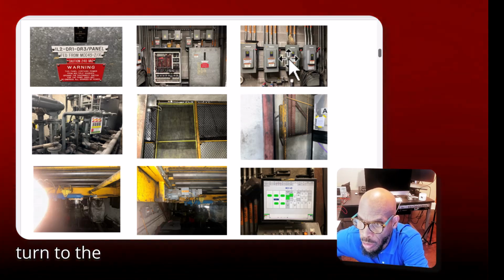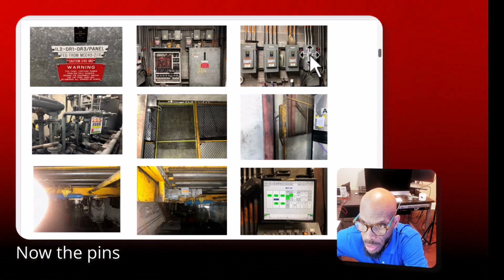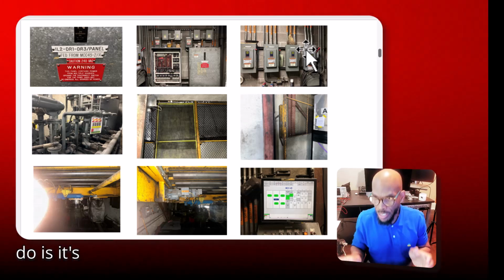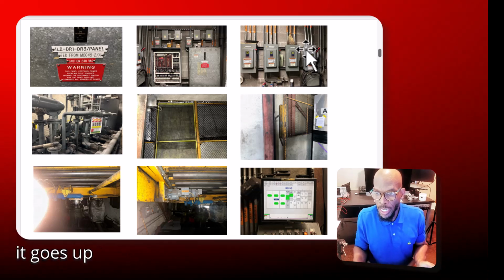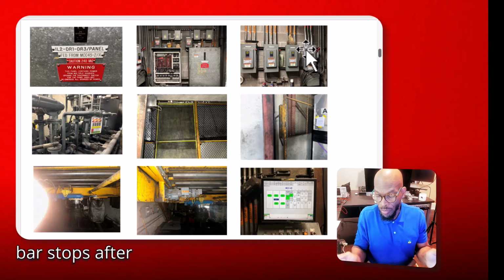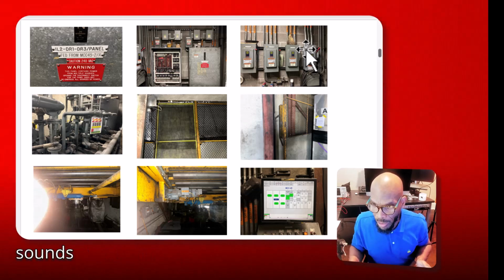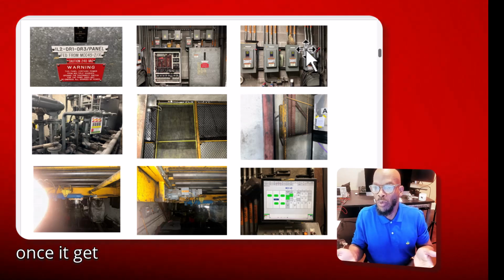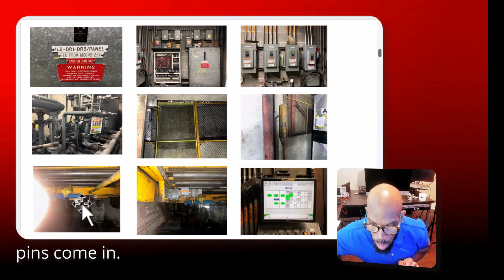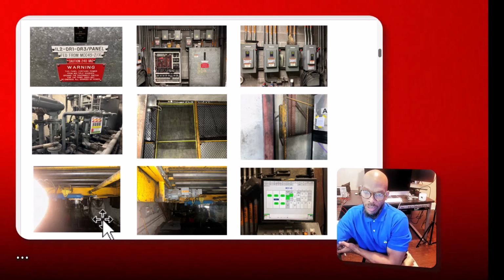Then if you turn to the left on the adjacent wall, you will see the disconnects for the pins. Now the pins go out and come in depending on what floor it's on. Because what the lift does is it's sitting on some pins. If it's on the bottom floor, it goes up a little bit. Once it gets ready to go, after the containers are in, the bar stops are up, the door is closed, and the warning horn sounds, then it starts to raise up. Once it gets up about a foot, the pins come in. That's what that blue thing does. It makes the pins come in. When the pins come in, the lift goes into high speed and goes upstairs to the 4th floor.